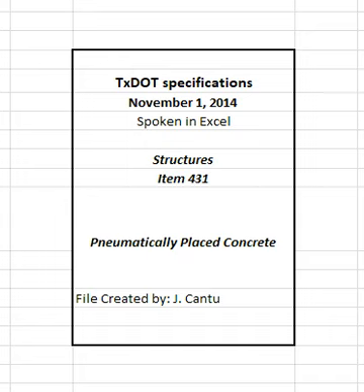Do not use explosive force to shoot anchors into concrete. Check the resistance to pull out of the reinforcing anchors when directed. Notify the engineer before installation of the anchors. Locate anchors so there is no damage to prestressing tendons or conduits embedded in the concrete.